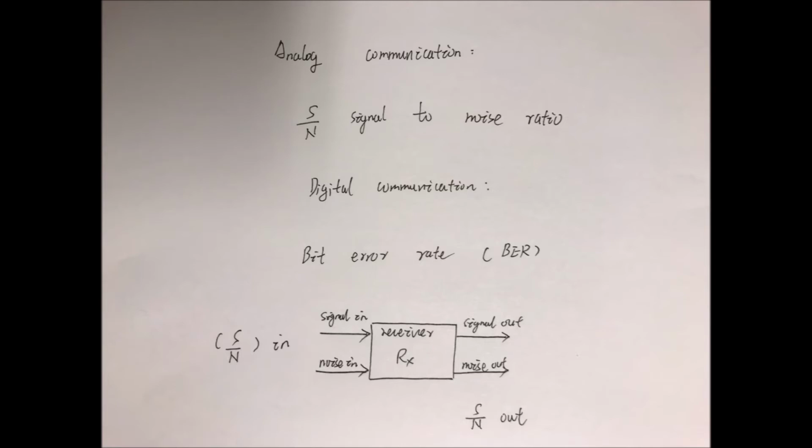Generally, wired communication like optical fiber, cable, and twisted telephone wire gives us pretty good bit error rate. For wireless communication, you can imagine, not very good. So all those techniques are most likely implemented for wireless communication, for example channel coding, source coding, equalization, spreading, and interleaving.